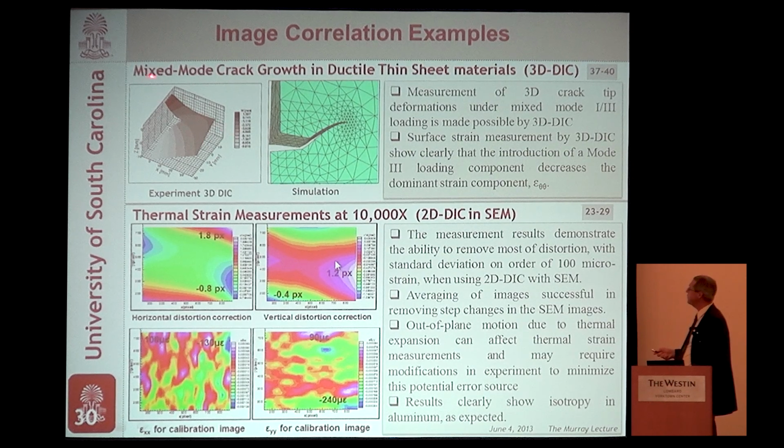The shape of this, the heavily distorted shape, comes from Jeff Helm, who did the work years back. And we can see that our finite element analysis, which is here, matched pretty well in general shape. The crack in this case was curving under large deformation, and we were seeking fracture parameters that worked under mixed mode conditions, mixed mode 1-2 and 2-3 and 1-2-3. Turns out it works really well with COD. That's the one we found worked well.